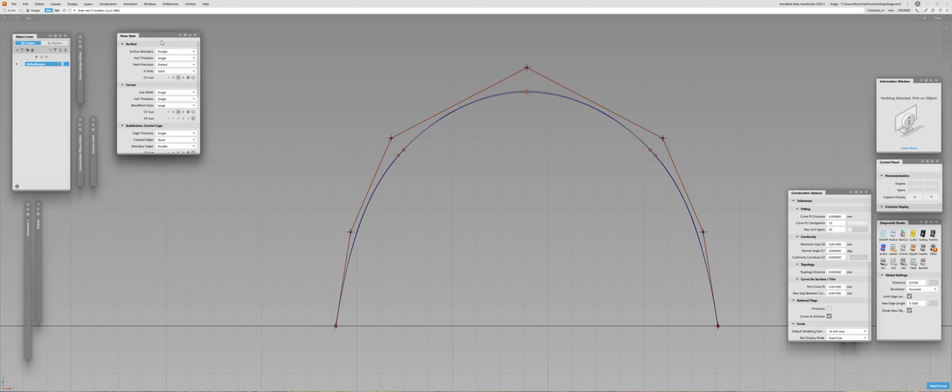So, as a conclusion, B-splines are a subset, let's put it this way, a subset of the NURBS mathematical model, which, as it stands today, is a global standard for CAD modeling. The construction of NURBS curves defined by CVs, basis functions, knot vectors, and weights is consistent. It is consistent across all CAD systems, not only Alias. And this global standard gives us designers